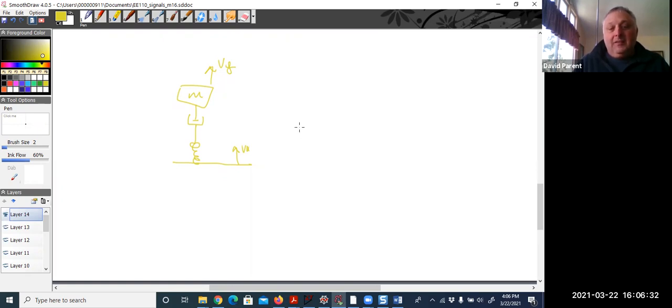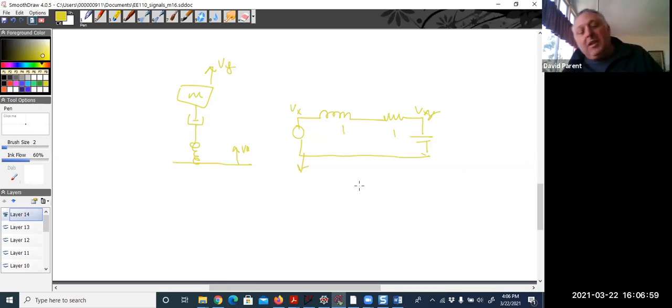I can actually turn this into a voltage, which represents velocity. The spring represents an inductor. The damper is a resistor. And then the mass actually is a capacitor. Instead of velocity, we measure voltage. And so now we can do our Bode plots, and determine over, under, or critically damped. What is the step response going to look like? Things like that.